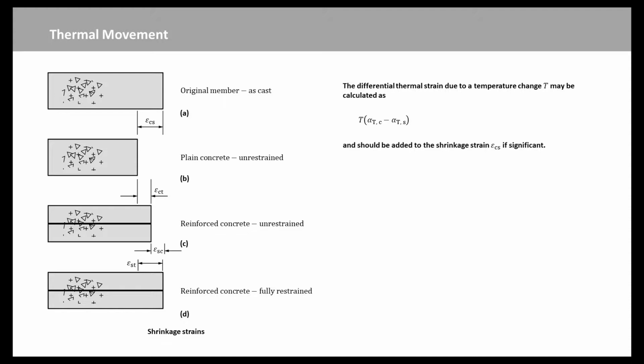However, the overall thermal contraction of concrete is frequently effective in producing the first crack in a restrained member, since the required temperature changes could easily occur overnight in a newly cast member, even with good control of the heat generated during the hydration processes.